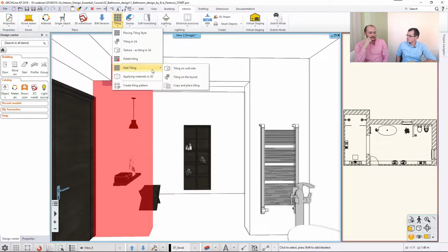There is an important difference, which you will see at the end of this session: if this were only a picture of a tiled surface, not tiles themselves, then the software couldn't calculate the number of tiles that's necessary to decorate a certain area. So it won't show up in the quantity takeoff. If you just add it as a texture, it doesn't count into the calculations. Yes. So if that's only a simple photograph of a tiled surface, it won't be calculated in the way it will be now when we do that.